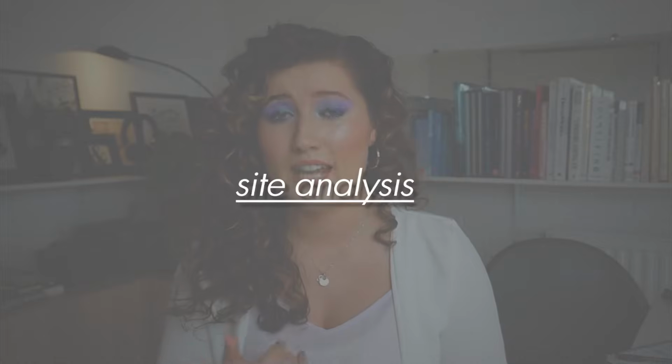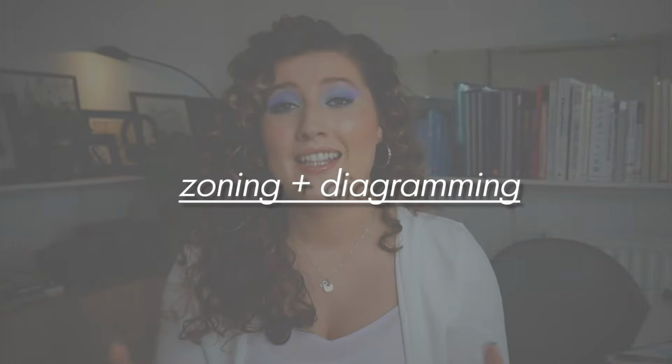So the first thing I do before doing any drawing whatsoever is put together a site analysis of the location and the site, which includes photos, sketches, a diagram, and of course we need all the measurements of the site. Once I've grasped a solid understanding of the site and location, I then move on to the next stage, which is zoning and diagramming. I think that before you go ahead and draw a concise floor plan, it's much easier to start off with basic shapes and do things in a blockier way. Let me show you what I mean.